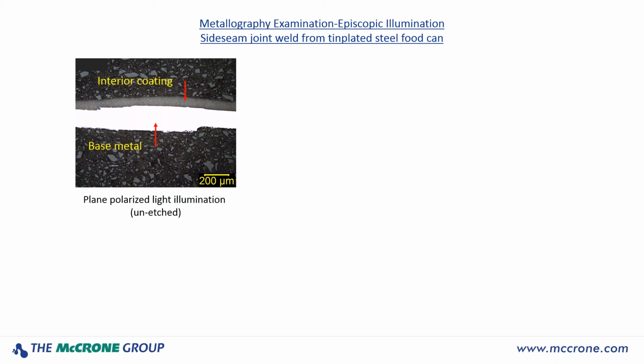In welding operations with metals, the weld becomes very susceptible to corrosion attack compared to the surrounding matrix metal. In other words, in the electrochemical sense, the weld becomes anodic and the surrounding metal becomes cathodic. Now when a corrosion reaction process starts, the corrosion reacts very rapidly within the anodic region, in this case the weld.